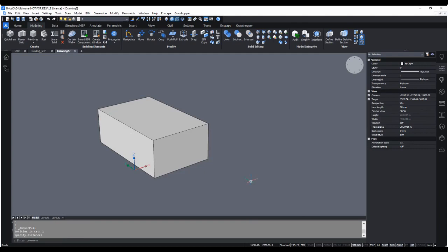Selection modes allow you to control which sub-entities, meaning faces, edges, and boundaries, should highlight in selection preview and can be selected. Selection modes can be found in a couple of places, including the Access 3D toolbar up at the top. Here we can see prioritize selection of edges, prioritize selection of faces, and enable boundary selection. You could also type in selection modes at the command line. And also we can see in the ribbon toolbar, again in the modeling tab, that we've got those 3 icons, the very last 3 icons on the very far right.